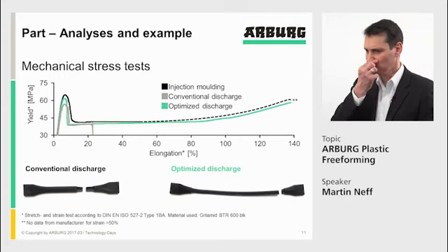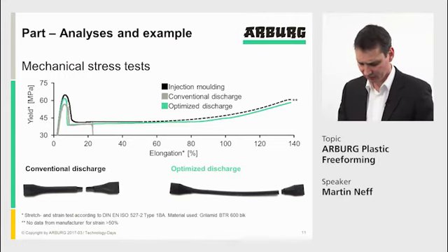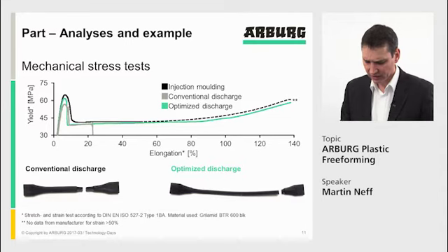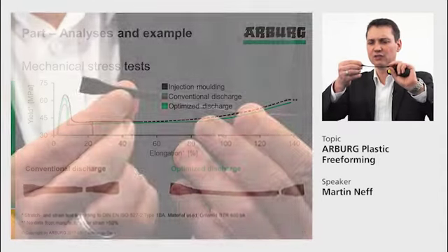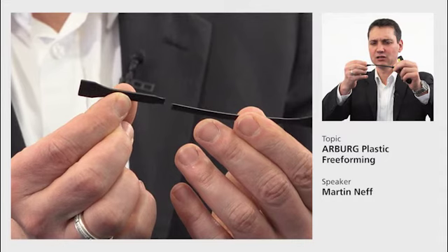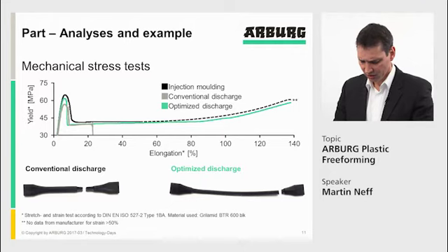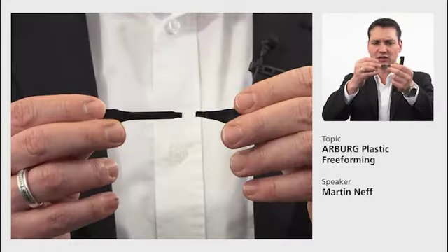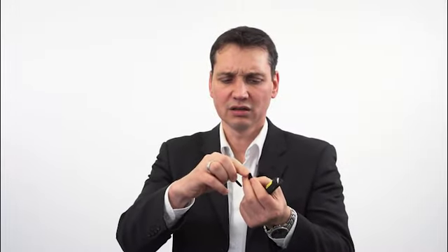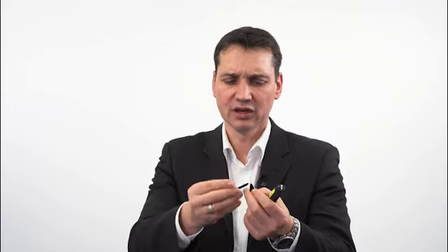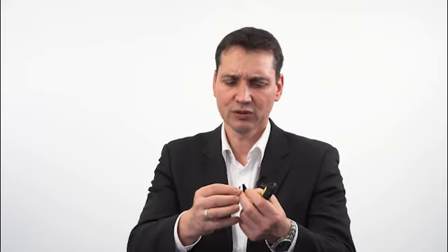How does it look? It looks like this, and I have this longer tensile bar with me. This is the tensile bar which had that longer elongation over 100%, and with a conventional one, we are looking at just this elongation before it breaks. You can really see in the breaking picture of the surface what the reason was for that. The reason was that the droplets are still visible and you didn't have that dense packing.